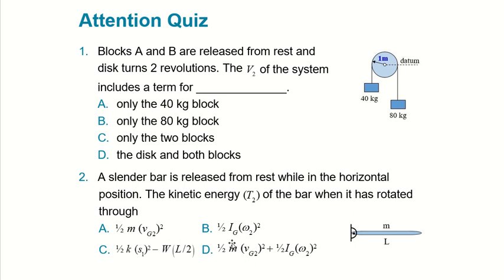So this is all gone, only B and D. Why? Because I'm seeing the angular velocity right here. Now your bar has gone through 2 types of motion, not only pure rotation. There's another part, which is your regular kinetic energy, which is in this total kinetic energy.